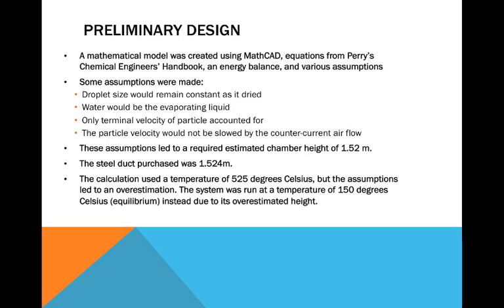According to Perry's, spray dryer chamber design is complex and sizing should normally be done by manufacturers. Due to the complexity of the design equations for spray drying, many assumptions were made to simplify the process. The team assumed that droplet size would remain constant as a droplet dried. An evaporation model was used for pure water, not milk. Only terminal velocity was accounted for in calculations, and the terminal velocity was calculated neglecting any resistance from countercurrent airflow.